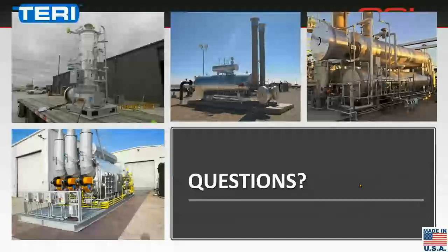So, yes, Denise, thank you for the question. On the instrumentation, we do have a separate presentation where we go into details, but you'll have your gas train, which basically, if you're taking your gas at the process outlet, you're going to cut it down to 60 pounds and then support your burner operation. In our case, we'll have the pressure at 5 psi to the burner.